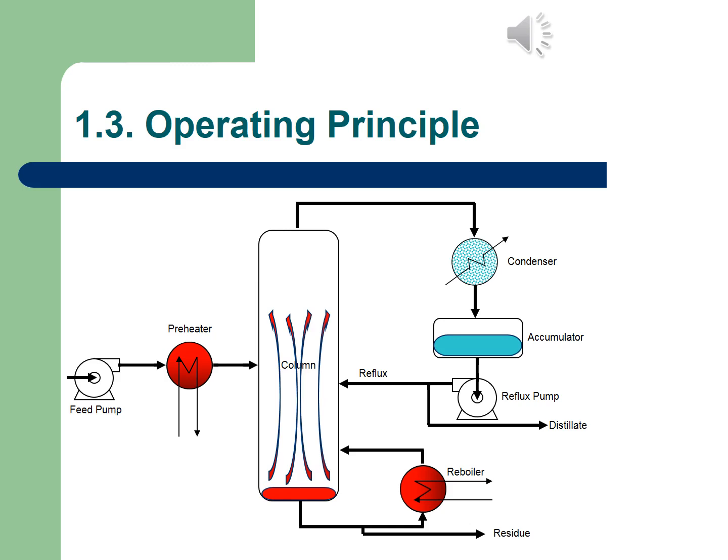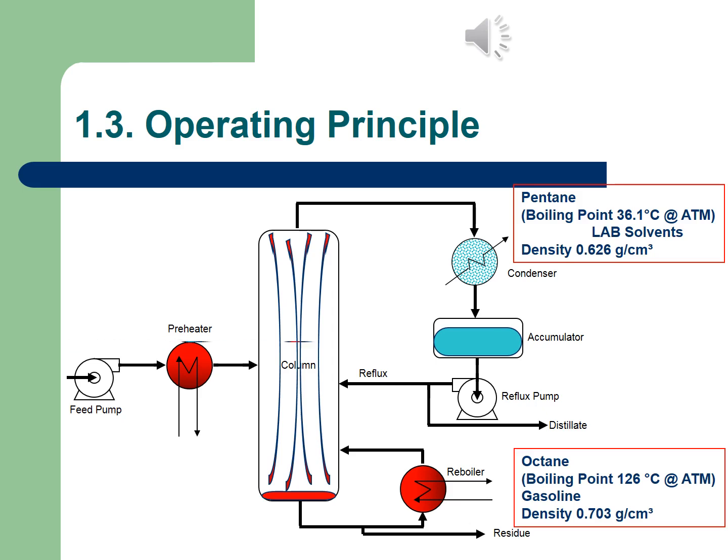And this is how the process then continues. Again, more vapor, more distillate in the accumulator, and eventually you're starting to get the separation process and a better purification because of the reflux, and also the reboiler, maybe again feeding back some of those components into the column.